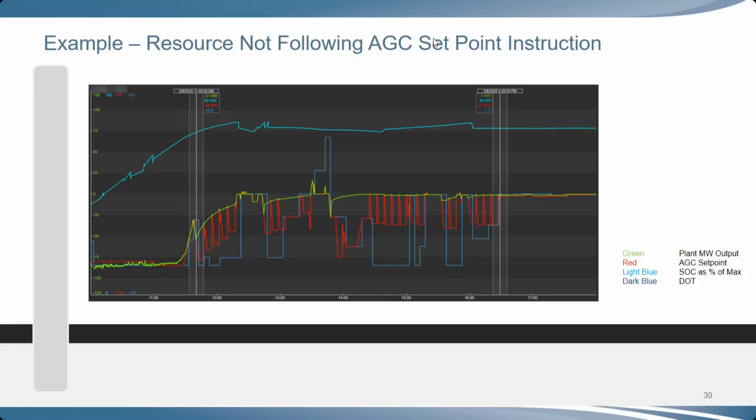That's super helpful, Drew. In the instance that we're being affected by an ambient condition, but a very slight one, let's say we have larger units, so I'm going to go with the 10 megawatt threshold, and it's at 5 megawatts. So we have a 5 megawatt ambient reduction in this hypothetical scenario. I just want to confirm that you're on the same page that there is no outage ticket required in that instance, and so there could be a slight delta of unavailability. What do you want to see in that instance for communication? As a generation dispatcher, I would like that you reflect your current availability with your resource in OMS.